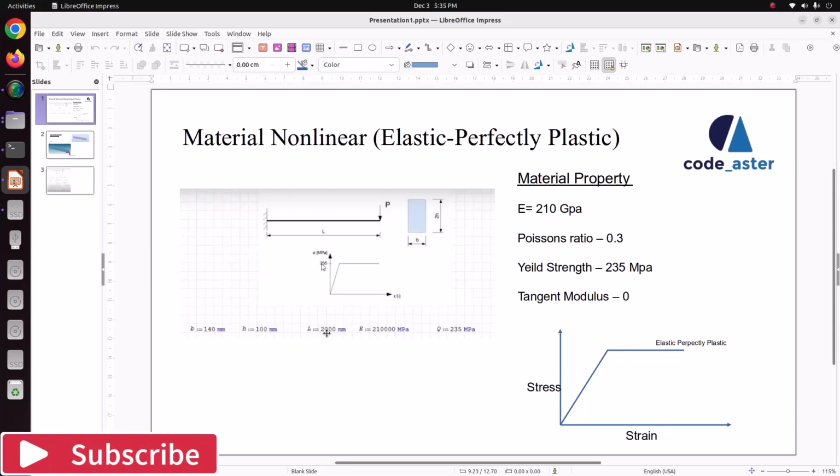In this tutorial, we are going to solve a material nonlinear problem, especially an elastic, perfectly plastic material using tangent modulus. We can say it is a bilinear handling. In ANSYS, they call it bilinear. Similarly, we are going to do bilinear handling.